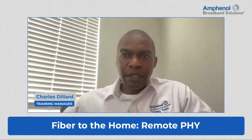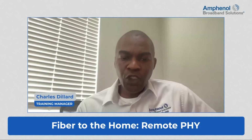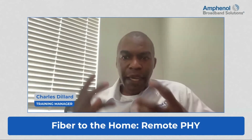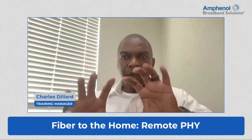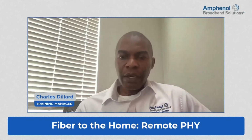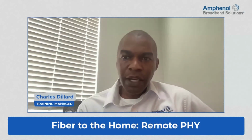If I step back a bit, with deploying remote PHY only, we're pushing the physical layer, which is the modulation, demodulation, or just creating the signal. But if we only deploy that and leave layer two in the head end, layer two handles the timing associated with devices at a subscriber's house. Cable modems rely on TDMA to have time slots in order to communicate back to the head end, so that one modem is not communicating at the same time as two or three other ones. If we leave the MAC layer in the head end and only deploy remote PHY, then for longer runs, we may have issues with timing, and that timing can cause errors out in the field.